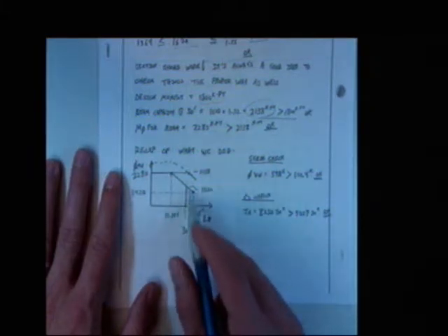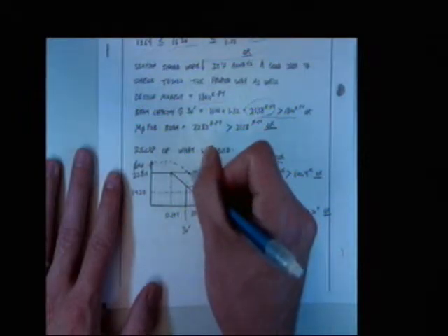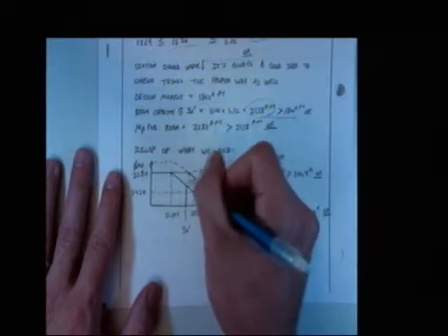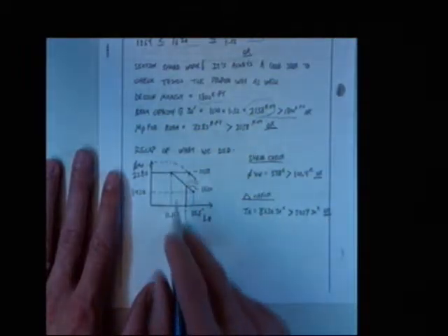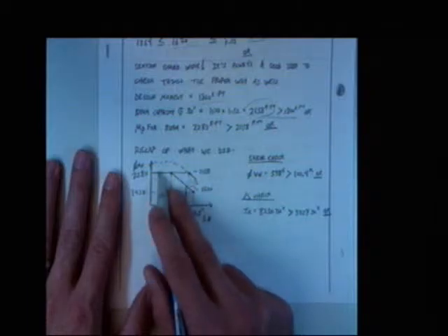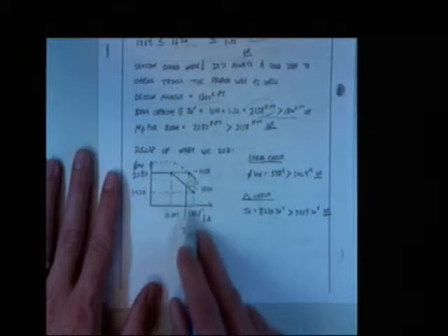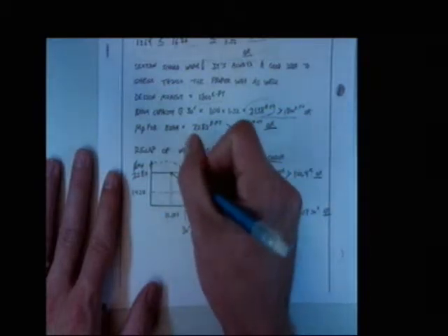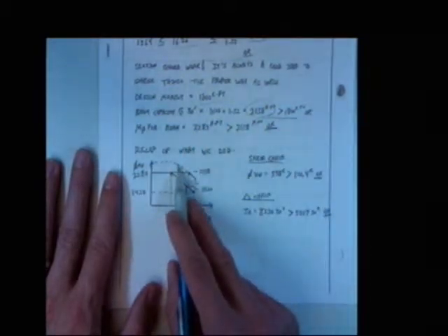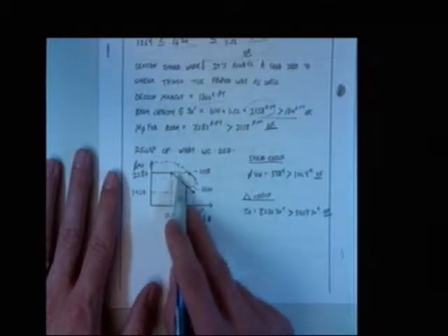This is the value of 1620 at 30 feet. I multiplied by my C sub B factor. That's the 1.32. That's what knocked me up. Knocked it up by 30%. It just so happens I was still underneath my phi M sub P, 2280 versus 2138. Does that make sense? If I, for whatever reasons, would have been here and tried to knock my value up to here, that wouldn't be allowed. I would have capped myself here.